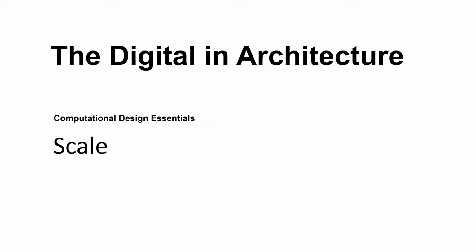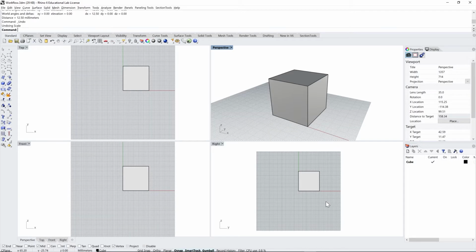In order to finish with our basic transformations, let's have a look into scale. In Rhino 6 you can use different scaling methods by scaling in 1D, 2D or 3D. So we can just go to the scale icon and open the cascade. So here you see the scale 3D, scale 2D and scale 1D. So let's focus on these three.